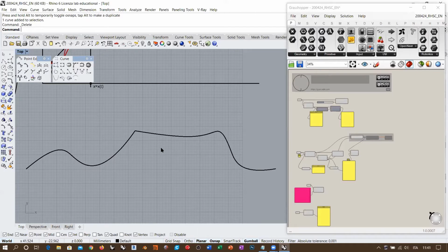So what comes next? Well, G0 is position continuity, G1 is tangency continuity. The next level is G2, which is quite a complex level of continuity, called curvature continuity. Now, the problem is that from G2 up, you have no possibility of creating this kind of continuity working directly with control points. And I'm going to show you this with another tool.